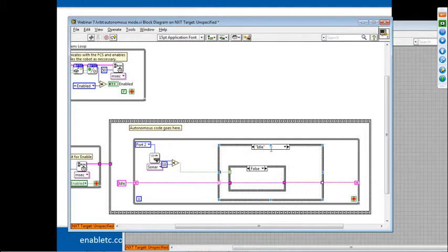So the next state we're going to implement is the start motor forward. We're going to take advantage of the false case that's been here by default. Call it start motor forward. It's a great time to take a step back, make sure we didn't spell anything wrong. Start motor forward, start motor forward. Perfect. The most likely cause of errors in this kind of programming are actually typos, so we've got to be careful. And in start motor forward, what we're going to do here is basically, well, start our DC motors.